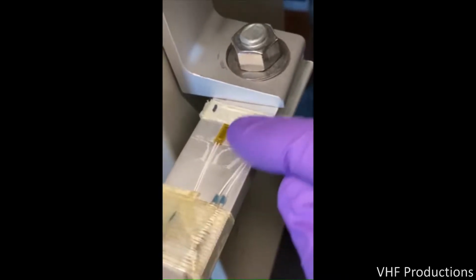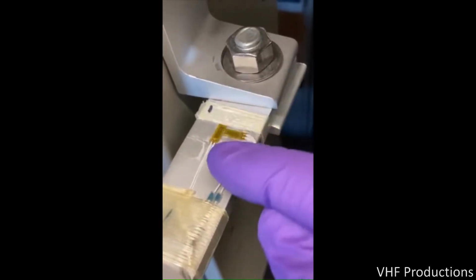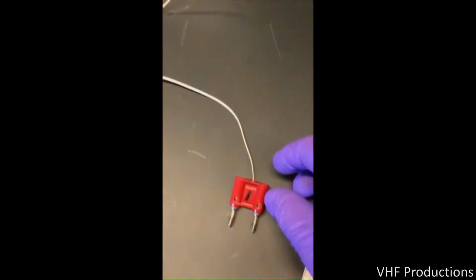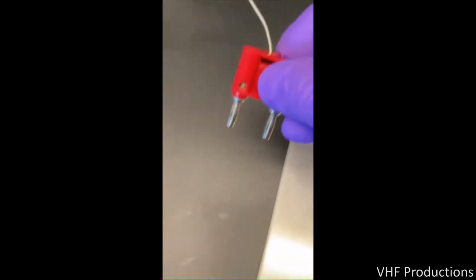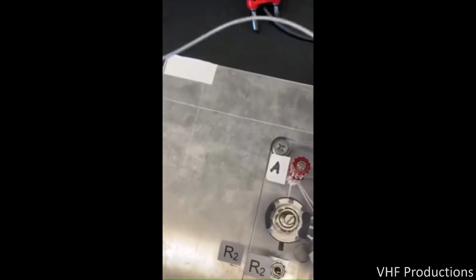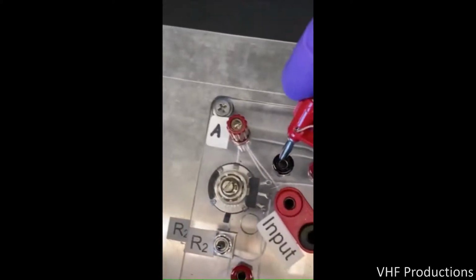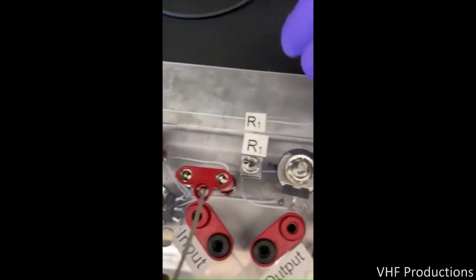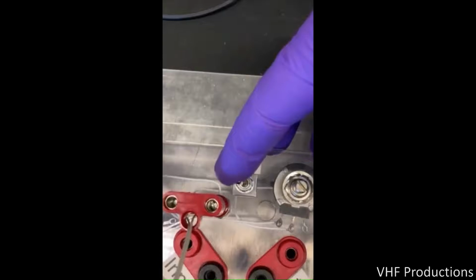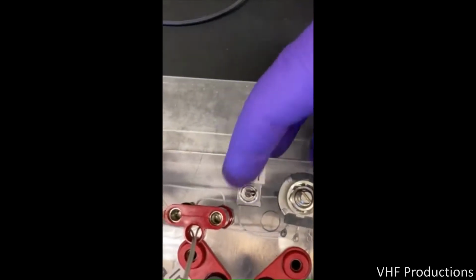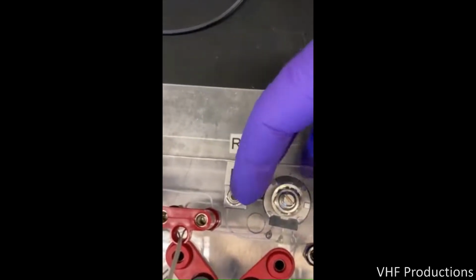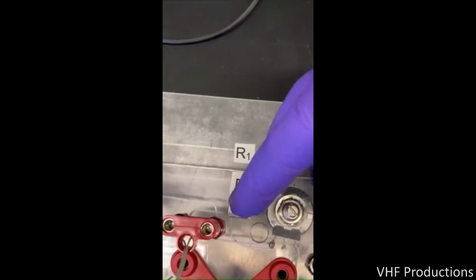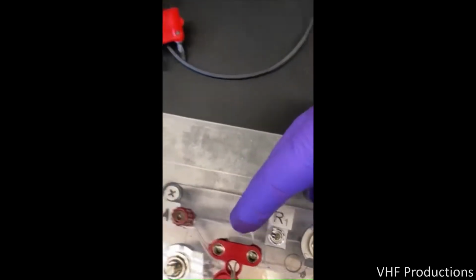Since the resistance of the strain gauge is very accurately 350 ohms, we need to set the potentiometers on each leg of the bridge to 350 ohms. We do that by putting in a connection across each side of the Wheatstone Bridge. For example, we measure the resistance between pins A and B and then switch to have the potentiometer, or the variable resistor, along that side of the bridge in that circuit and adjust the resistance to exactly match 350 ohms.